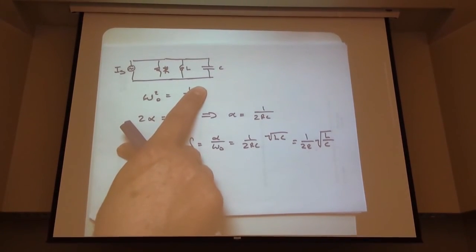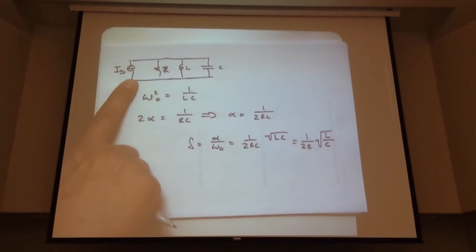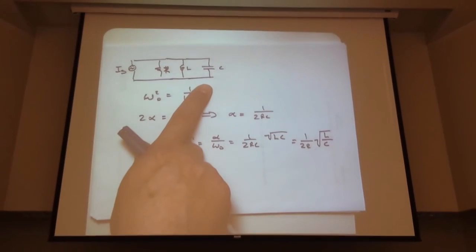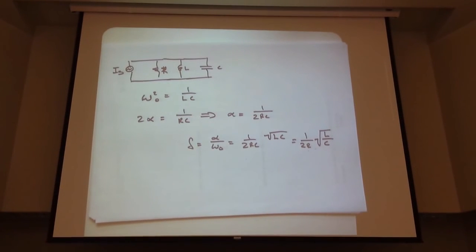If the admittance is zero, what's the impedance? And if we have infinite impedance and we're driving a current through it, what's the voltage? It's kind of a trick question, but what's something times infinity? Ohm's law still applies. You have infinite voltage, right? All right, not something we can really do.